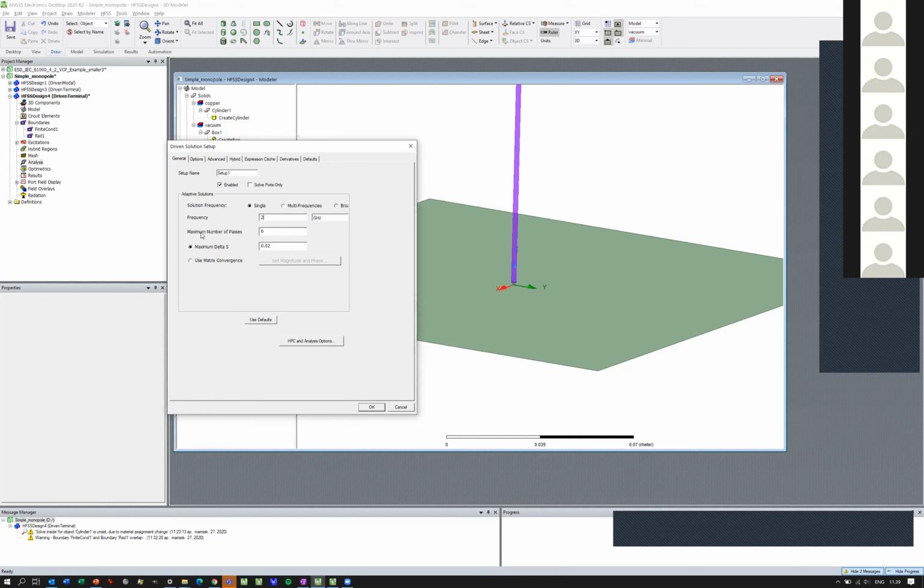And then this says how many iterations we are doing in order to increase the meshing. The maximum is 6. I will say that you can do 9 iterations, and this is how much error for the meshing we let it be. I will keep the default 2% here, and that's it. That's the only thing you need to specify here.